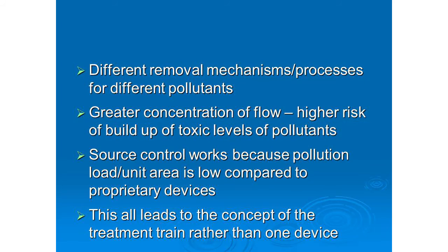So one of the overriding principles of SuDS and source control is to keep everything spread out. And the reason they work is because we're keeping everything spread out. So there's a lower load per unit area of SuDS in terms of silt and pollution. And that's why source control works. That's why SuDS work and why they're shown to be so effective.